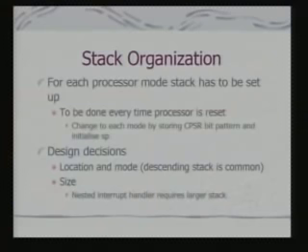Okay. So, change to each mode. During reset mode you change to each mode by adjusting the CPSR bits and then writing the correct value onto SP. The other decision, and this is a design decision of a software developer, is where in memory the stack is to be located and what mode is to be adopted, because I can have all possible modes of stack. Typically a descending stack is the most common mode, and the location is defined in such a way that you really do not have a chance to overrun the vector table, and that is very, very important.